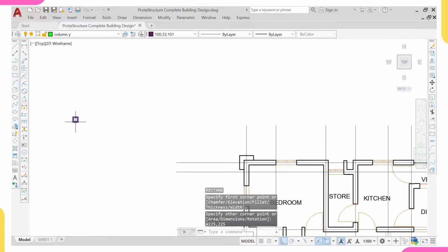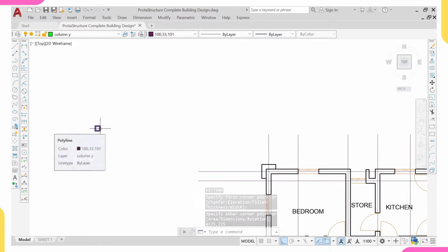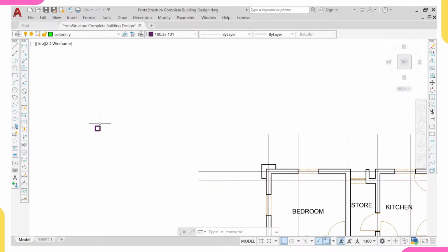Yeah. So since I've gotten this, let me also say something. Column placement is solely dependent on the engineer. Yes, my column placement can differ from your column placement. But the thing is that the engineer needs to follow the governing principles in column placement in order to place his columns well. Because once it comes to structural design, two things are of necessity to us. First, safety. Second, economy. If your building is safe but it is not economical, you are not a good structural engineer. But safety is our priority.